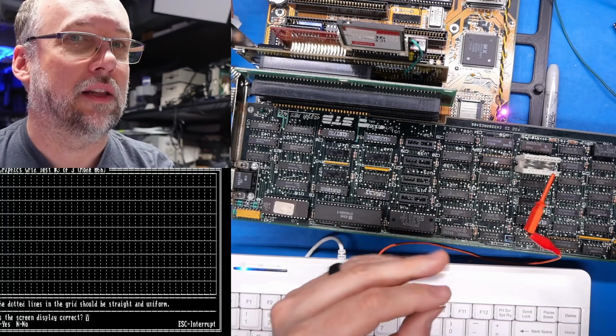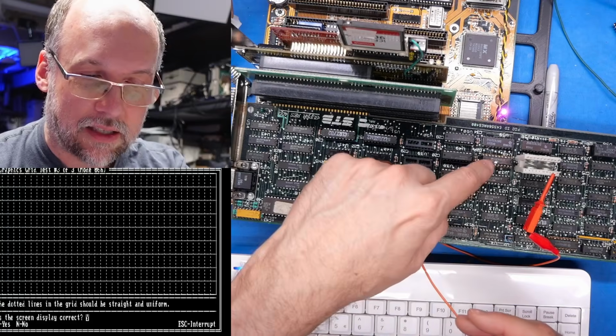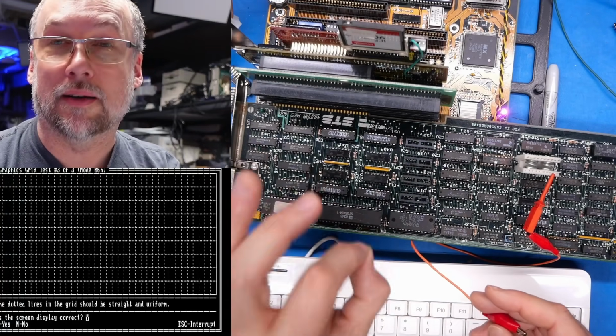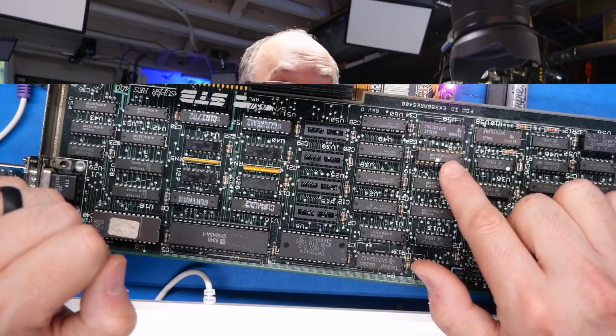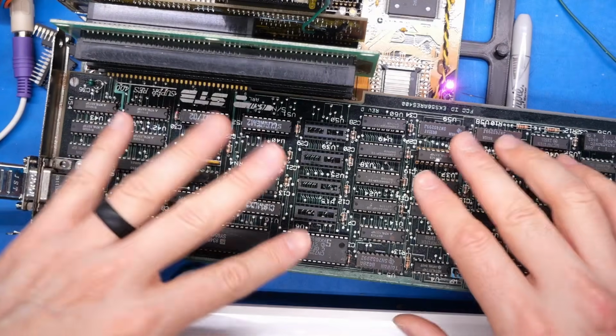Yeah, it doesn't really do anything, because this chip here, and I guess this flip-flop, is solely responsible for the attribute bit. So I think what happened here is that the chip I took out is one chip beyond where the problem lies. And I have a feeling that this chip is only handling attribute-related stuff, which is why it had no effect on the graphics. We're onto something here with this, but I need to find where this goes.